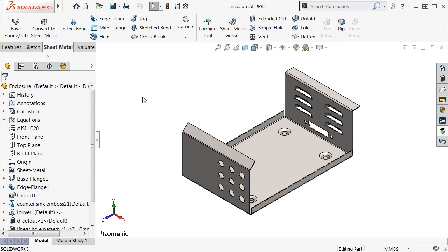When you're creating drawings for sheet metal parts, you start the same way as you would any drawing. You insert drawing views, dimensions, and annotations to communicate the design with others. This includes adding dimensions for the inner bend radius, creating detail views to show corner treatments, and adding punch tables to give details about library and form features.